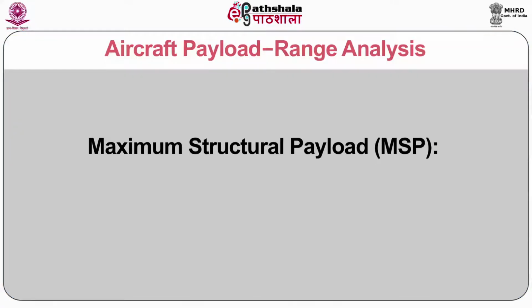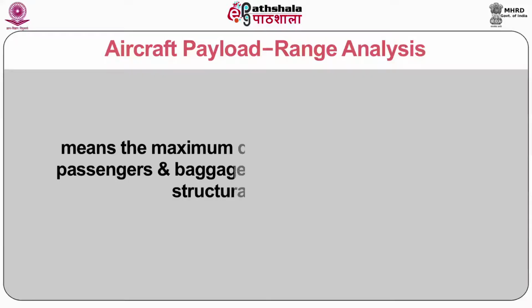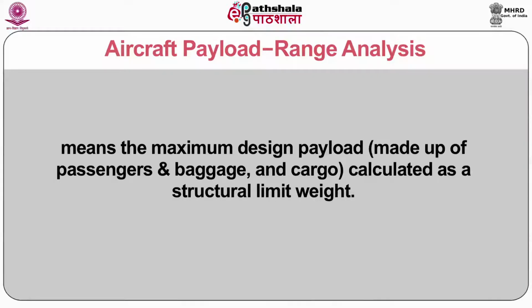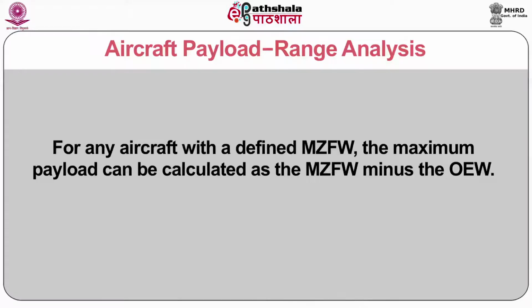Maximum structural payload, that is MSP, means the maximum design payload made up of passengers, baggage and cargo, and calculated as a structural limit weight. For any aircraft with a defined MZFW, the maximum payload can be calculated as the MZFW minus the OEW.